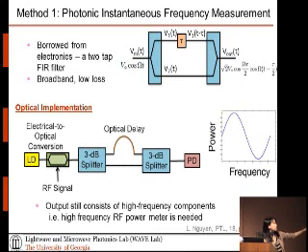The first part is just what I described to you earlier about the high-level architecture, which is the electrical to optical conversion. It consists of a laser and modulator, which takes the wireless signal or RF signal. Then we use an optical splitter to split into two branches, and one of the branches uses a fiber or some kind of delay line to delay it, and then we combine it together and detect it using a photodetector.